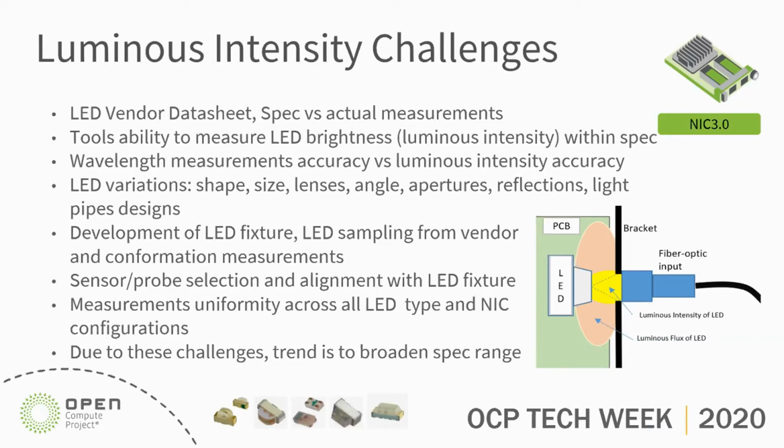Measurement uniformity across all LED types and NIC configurations showed, with some observation, significant differences on green and amber LEDs. At the same level of millicandela, LEDs behave a little bit differently, and to establish that difference, further research was required.